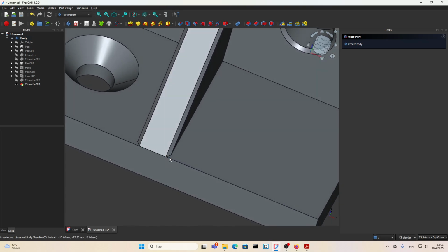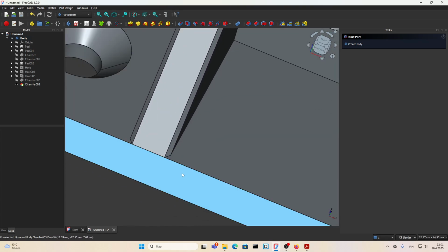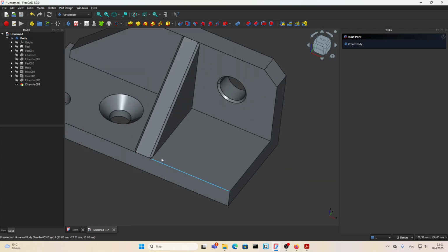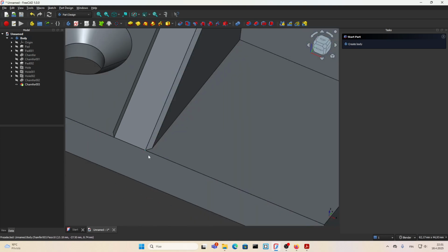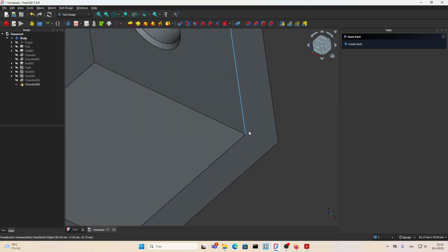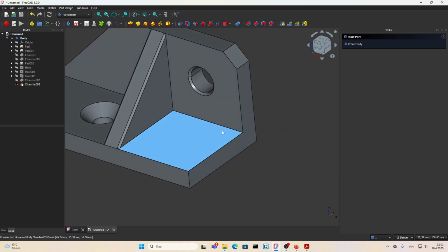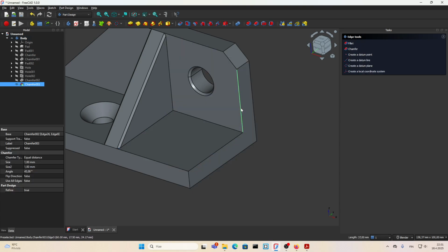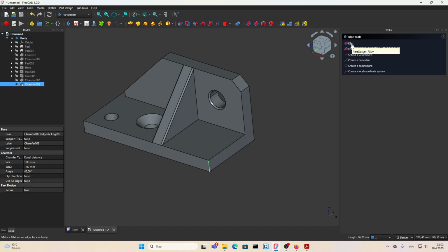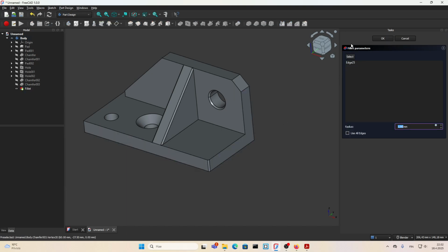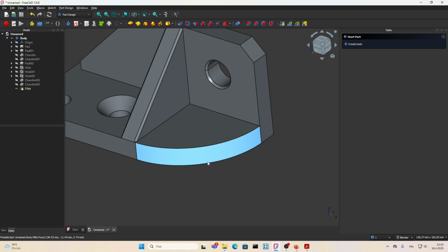See what happens? It looks like this. This is the chamfer. Now when I'm going to fillet it, the fillet is going to be in here. So it's not going to affect this one and it's going to work. Same thing in here. In here, I have to make a fillet, but I will not do it right now. I will just make it like this. I will show you. Let's learn by making mistakes. Click on here, fillet 45. See, the model didn't get destroyed.